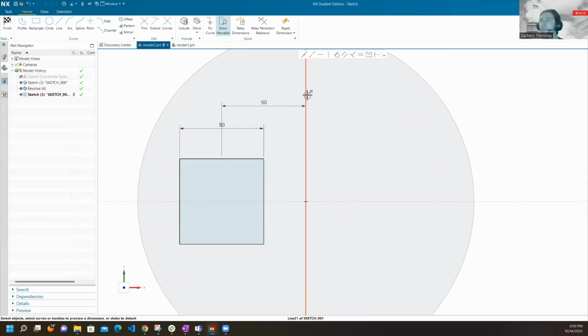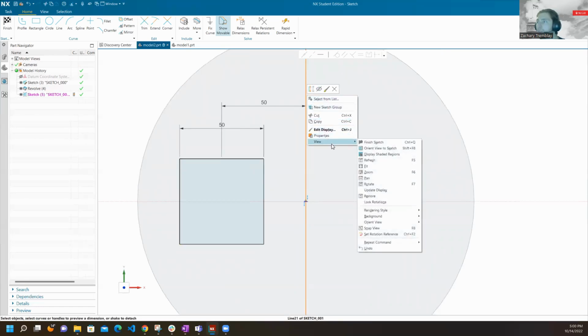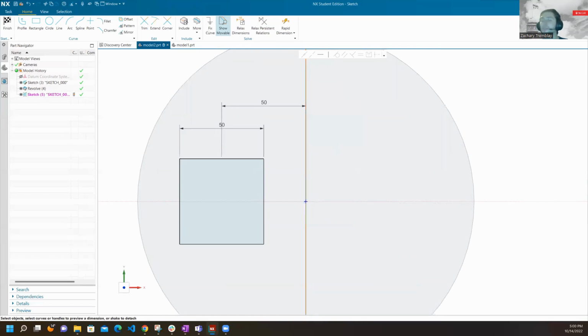So what we do in this instance is right click on the line and say we want to convert it to a reference. Where's the convert to reference? Let me just find the function. As always, when I'm lost, I can just use the lookup function over here.